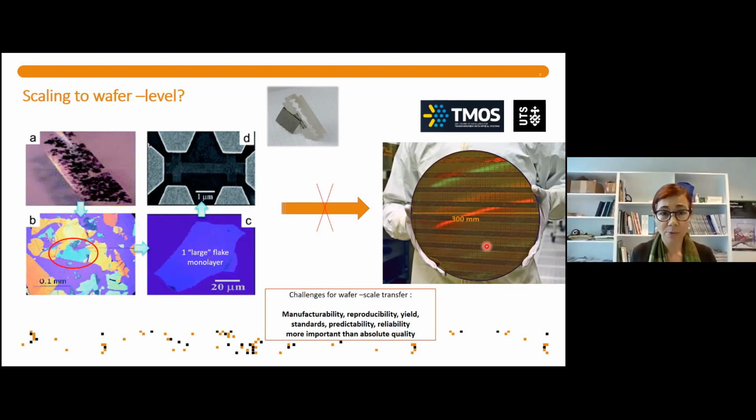Delamination is going to be a very important factor because, being a 2D material, the layer is only held together by van der Waals forces to its substrate. And clearly you can understand van der Waals forces are strong, but they're also pretty weak in terms of semiconductor processing. So delamination is something that happens very easily through the many, and I'm talking about hundreds of wafer level steps that need to happen before having the final product, maybe an integrated circuit of any type.